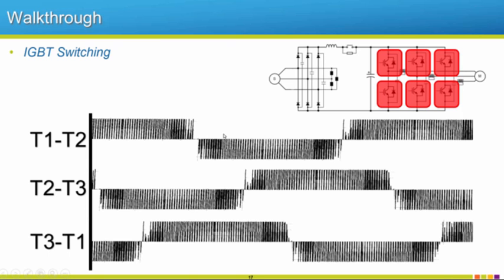There. So you notice how on these first two, which is for this waveform, this upper waveform, just this top one was firing, okay? This bottom one will start firing, but we haven't reached that point yet. So if we go down to T2, T3, you're going to focus on these two. This is the upper portion of that waveform. This is the lower portion. So this one should come on just for a second, and then this other one should start switching after that. So let's see if that happens.